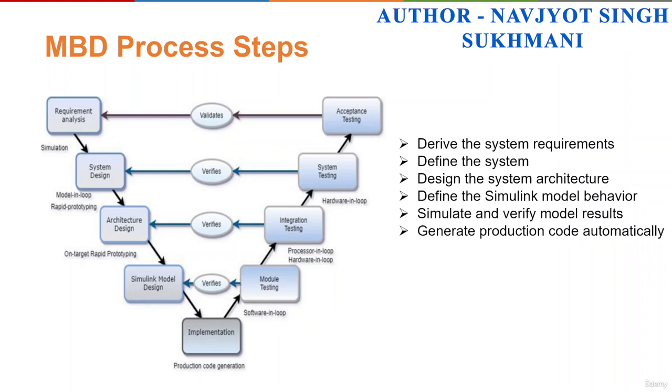Autocode generation reduces errors due to manual code writing. The behavior results of generated software code simulations are compared with the model simulation results, and the model design and parameters are adjusted accordingly to get improved performance.